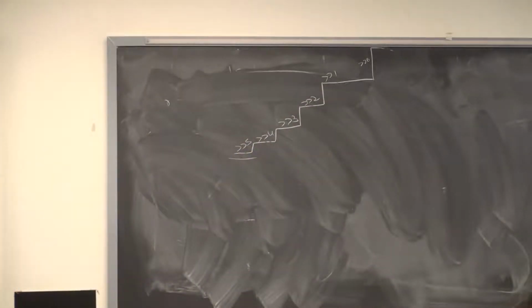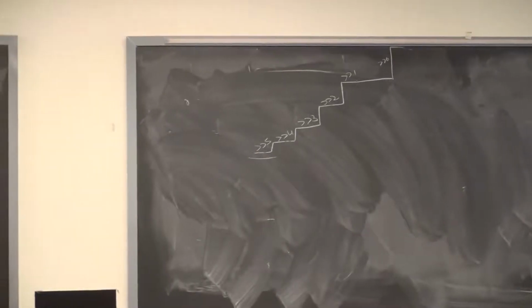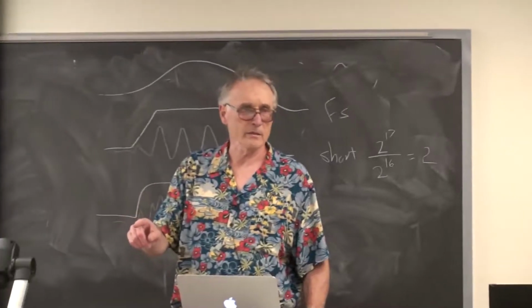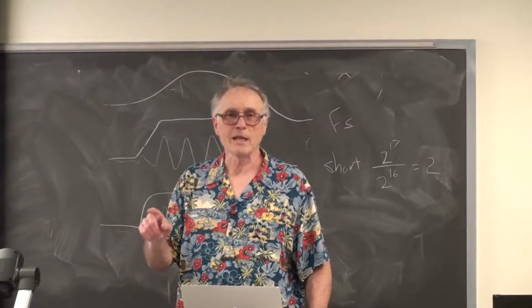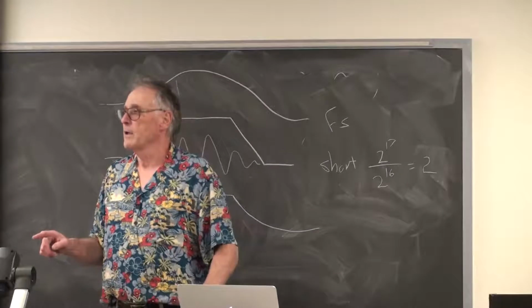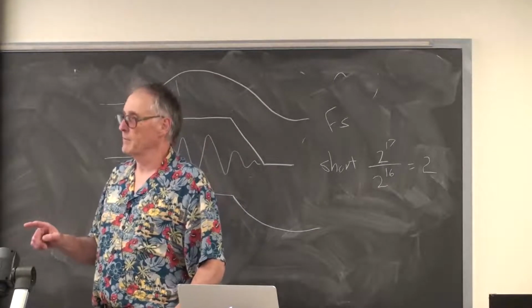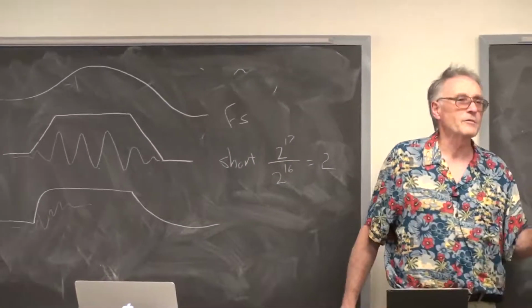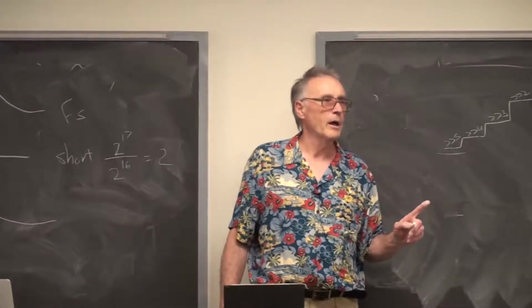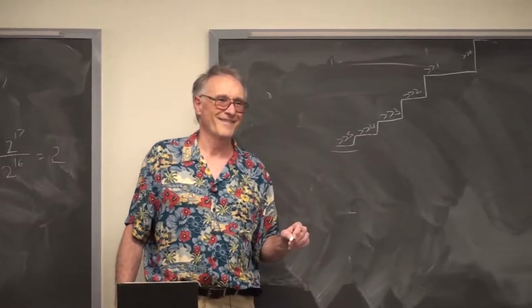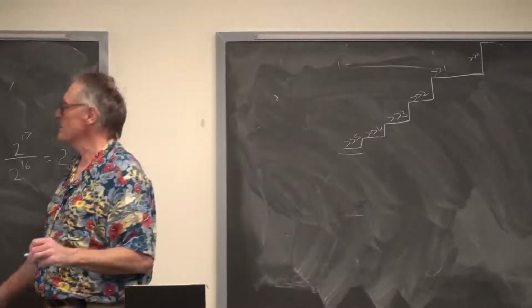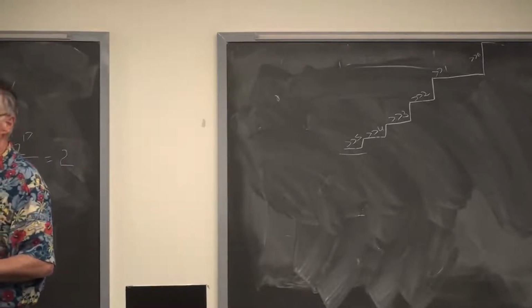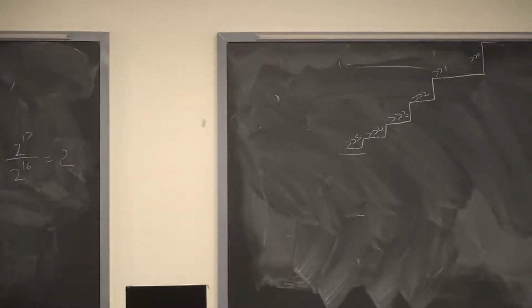The arithmetic is extremely cheap, and it actually sounds rather good because your ear has an exponential response. Your ear is not linear with amplitude. It responds to the log of the amplitude. And so by making exponential steps, it sounds like a linear ramp. So that's a possibility instead of using a per sample linear ramp.